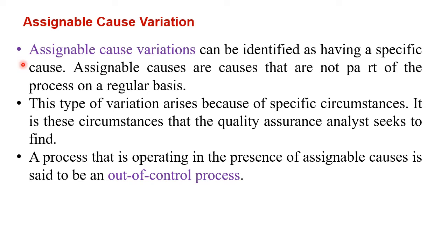So in other words, this may occur because, let's say, for example, you have one operator on a specific piece of machinery, and you hire somebody else, and he takes over. And you find during your quality analysis that something's changed. Well, one cause may be that the new operator needs more training. So if we find that out, we can assign that variation. It's an assignable cause. We know what caused it. It's just not random. It's specifically tied to something we can identify.